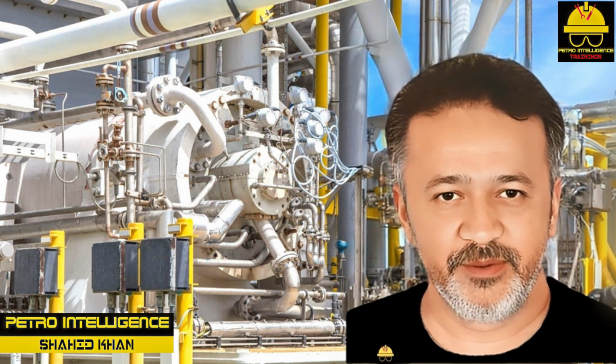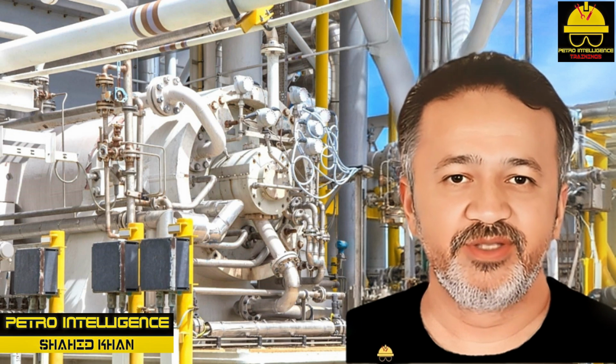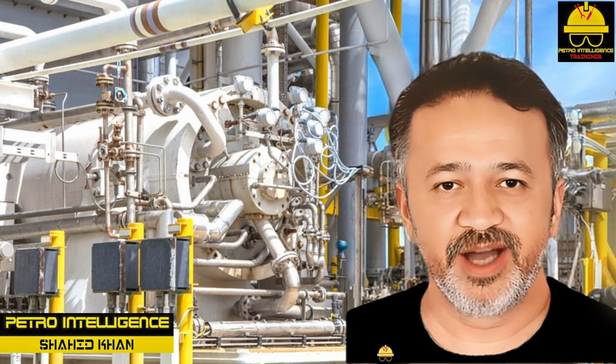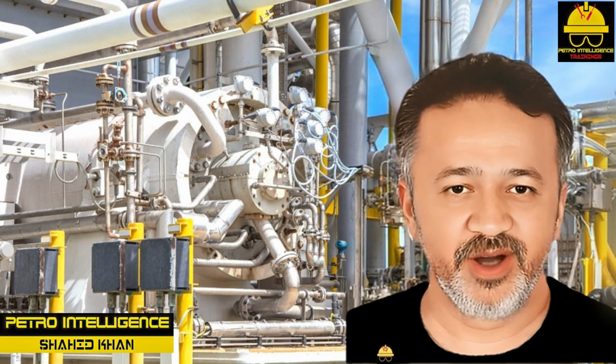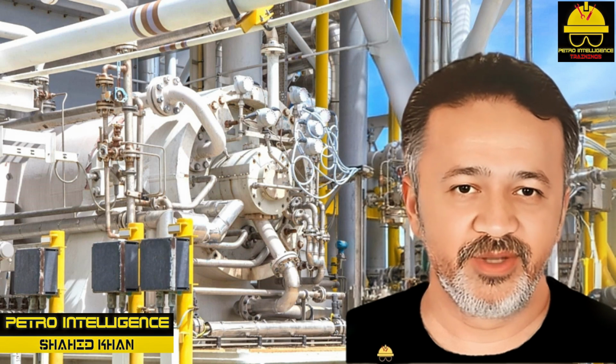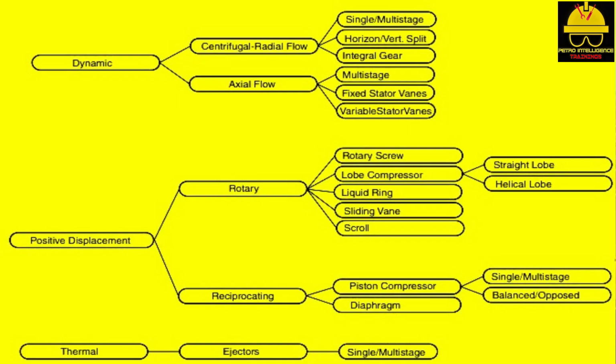In a refinery or chemical plant, compressors are used to compress gases such as light hydrocarbons, nitrogen, hydrogen, carbon dioxide, and chlorine. These gases are sent to headers, from which they are distributed to a variety of applications. There are 3 basic designs for compressors as shown in picture: dynamic, positive displacement, and thermal. Dynamic compressors include centrifugal or radial flow and axial, straight line, flow compressors. Positive displacement compressors include rotary and reciprocating compressors.